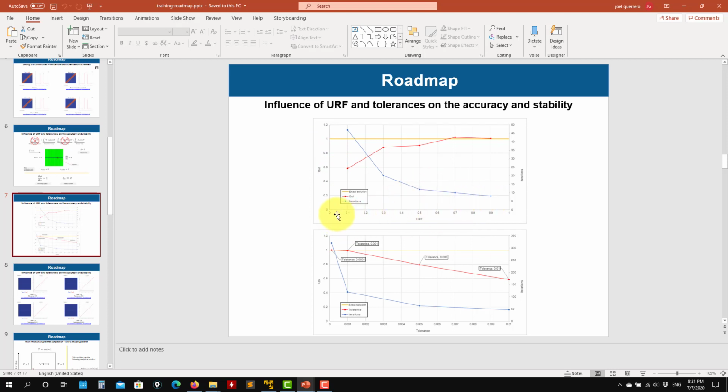See, as we increase the under-relaxation factors, we get a faster convergence rate. See that with 0.9, in just about 10 iterations, we get a converged solution, and we get something close to the actual value. But as we decrease under-relaxation, we use more iterations. And mysteriously, as you decrease it, we are also getting farther from the actual solution.